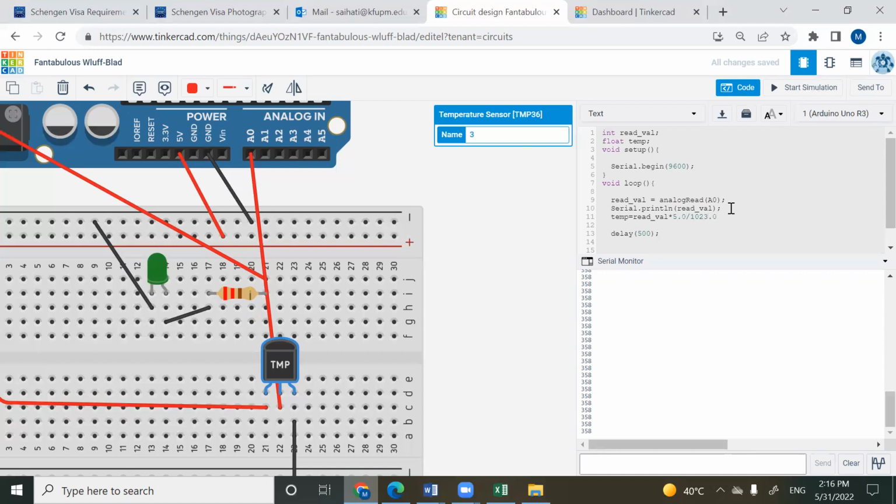Here, actually, I did not convert it to temperature yet. 0 to 1023, since the minimum is 0 volt and the maximum is 5 volt. So this should go to 0 volt, and this should go to 5 volt, right? If I make it this way, do you agree that I'm converting this to voltage? Yes. So I did not yet convert it to temperature.